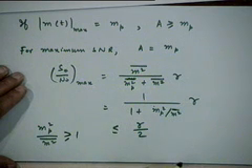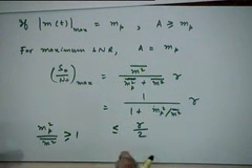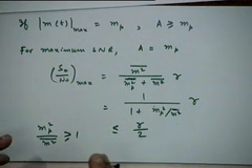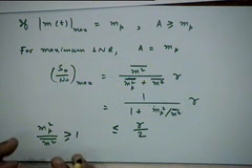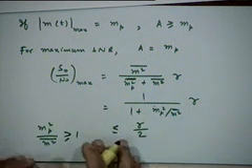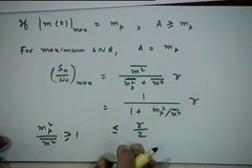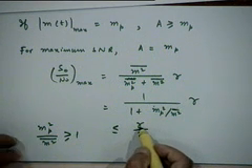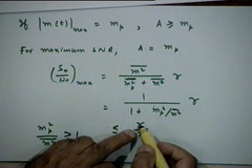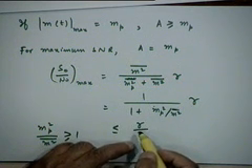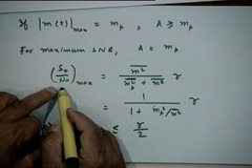This is of course a very rough bound, but what it tells you is that there is at least a 3 dB disadvantage, a 3 dB cost associated with use of carrier compared to not using the carrier. That is, I must require at least 3 dB more power, twice as much power for transmission. Gamma should be at least twice as much as earlier, so as to get the same value of the SNR.